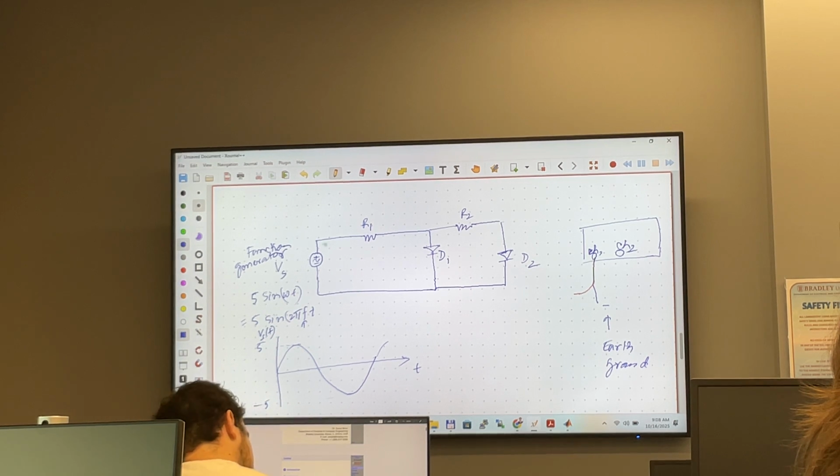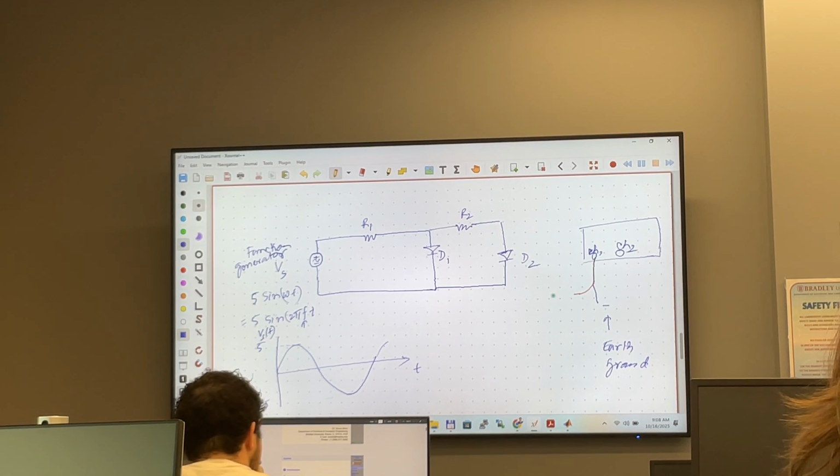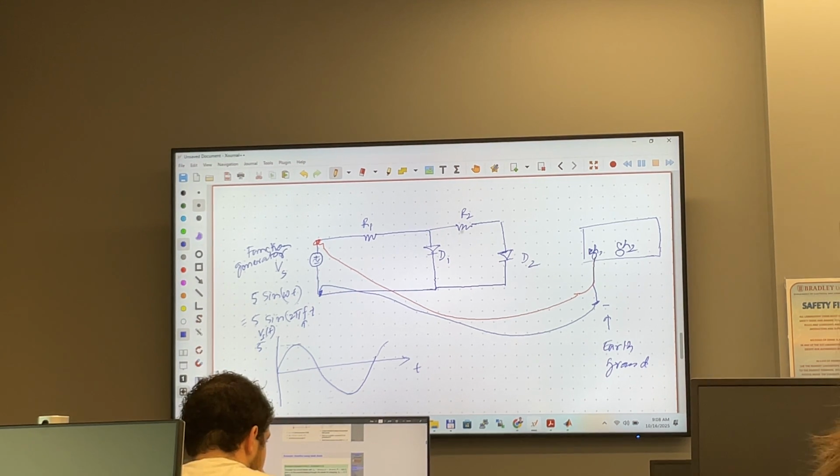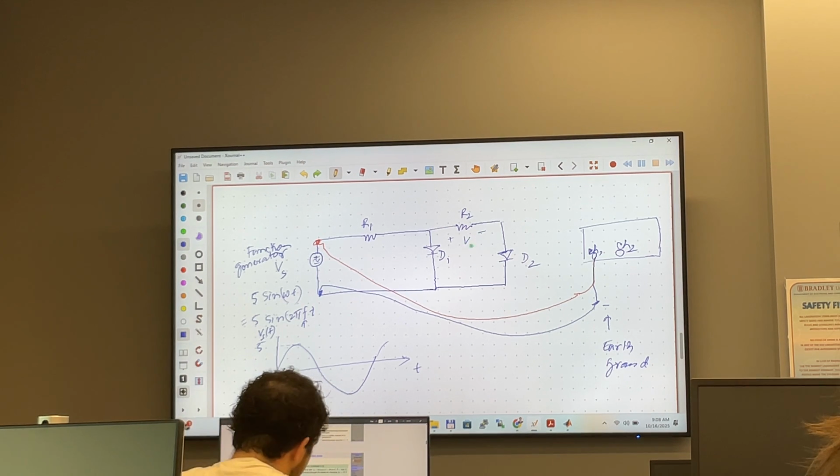So when you show the voltage signal in channel 1, you put this channel 1, you connect it right here, and your negative, you put it right here. That way you see the input signal on channel 1. Now, if I ask you to show the voltage across R2, which is identical with V2.